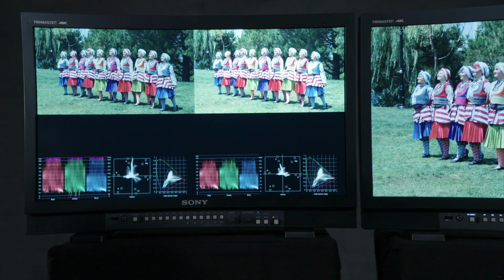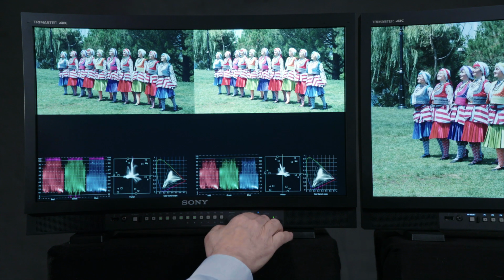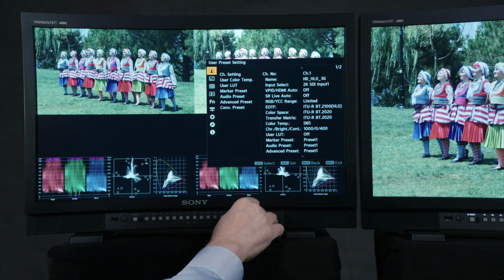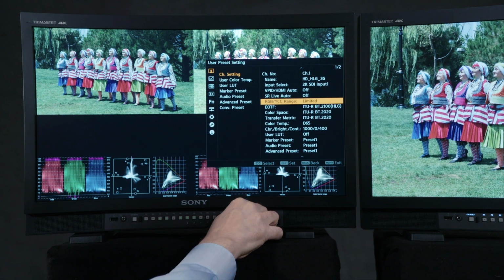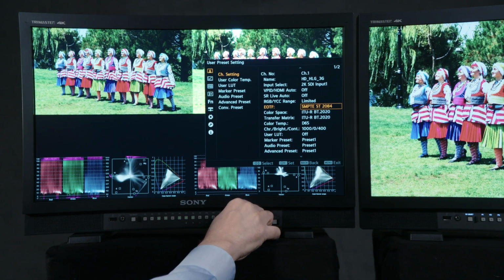Also, we've been only talking about live production and conversion from HLG or S-Log3 into SDR 709. As mentioned earlier, but worth repeating, for a different class of applications, such as on-set or movie production, one can set the EOTF for PQ, ST2084, in the Channel Setting menu, corresponding to a PQ input source, and to show its conversion to SDR 709. To do this, same as before, set up your input EOTF in Channel 1 to SMPTE ST2084.